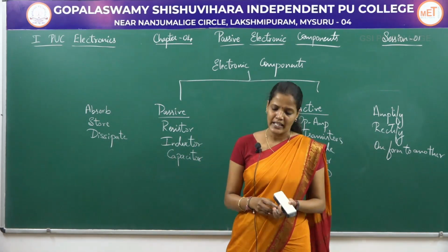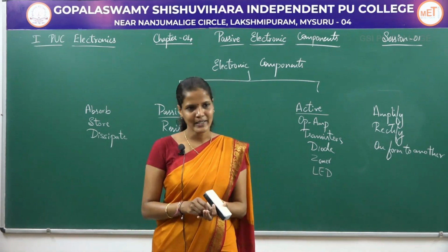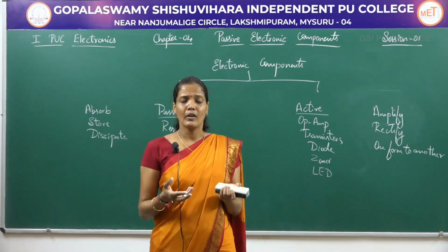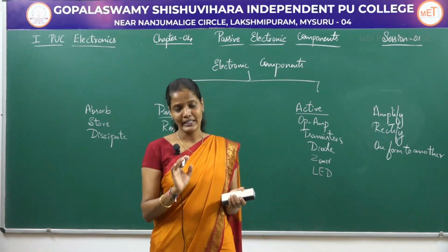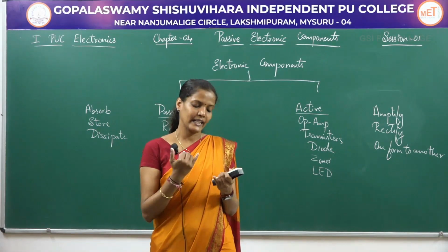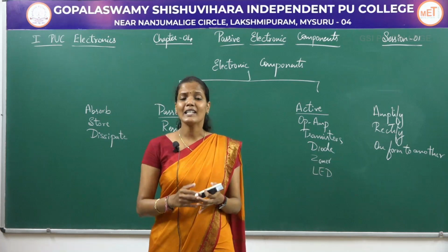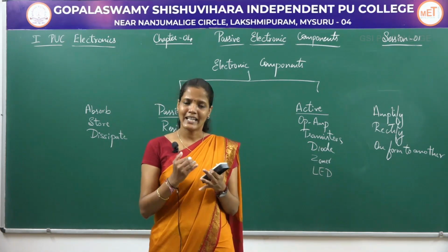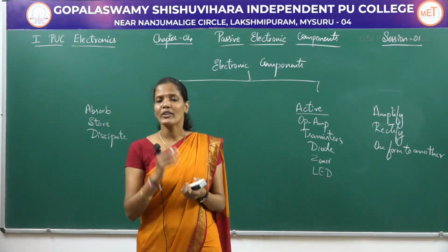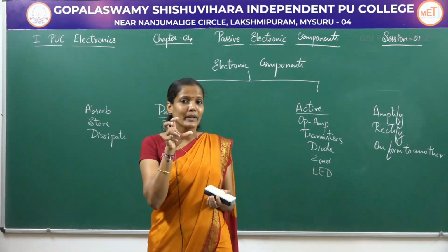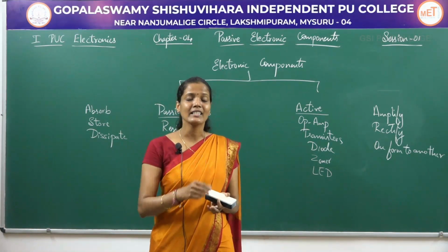Coming to this rectifier. Rectifier is nothing but the process of converting AC to DC. Whatever the supply we are getting through the electricity board, that is pure AC. But some of the appliances like our mobile phone or a computer, there are a number of electronic devices or the electronic goods we use in our daily life that require DC. So we are going to use a separate circuit called a rectifier which converts that AC and gives us DC.